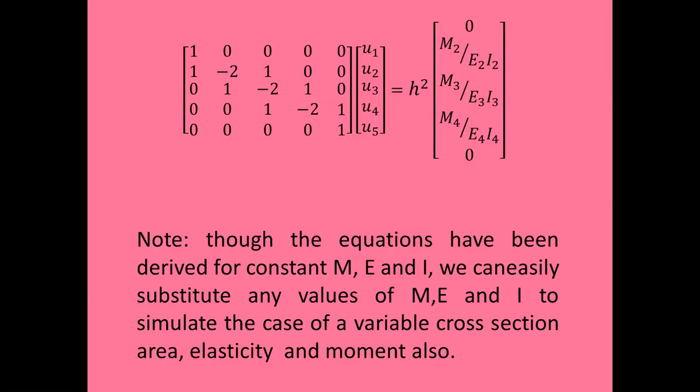Now the thing to be noticed is, though the equations have been derived for constant M, E and I, we can easily substitute any value of M, E and I to simulate the case of a variable cross-section area, elasticity and moment.